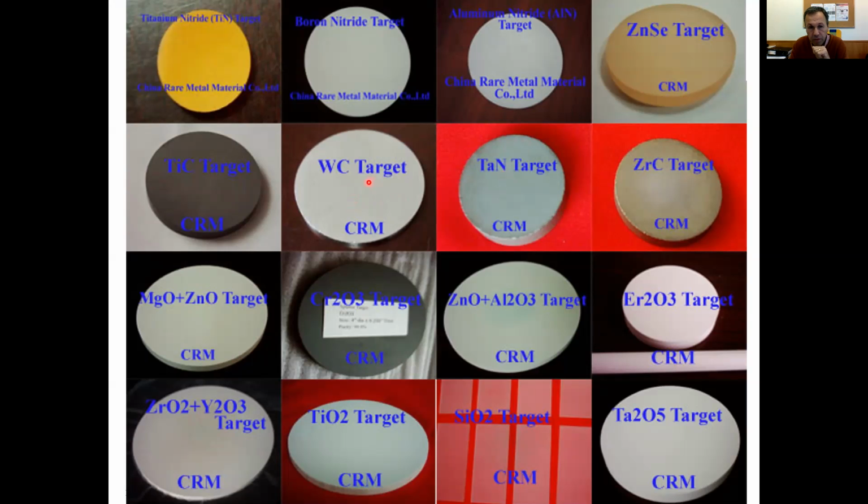If you want to produce coatings for wear prevention on cutting tools in the industry, to cut metal sheets, for example for the automobile industry, these cutting tools wear very easily. So you have to produce a coating which is very hard and also has lubricating properties. Tungsten carbide is very good to produce these kinds of coatings, or titanium carbide also. This is a titanium dioxide target, which produces self-cleaning materials. And you have other kinds of examples here.